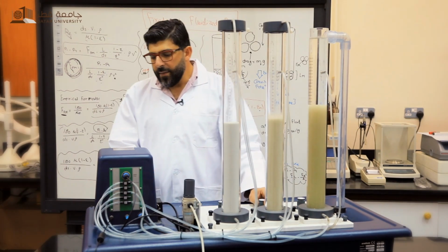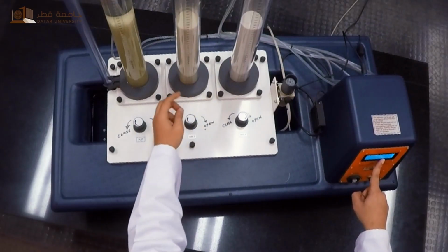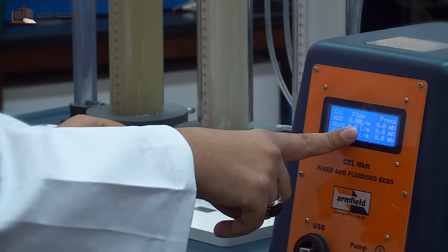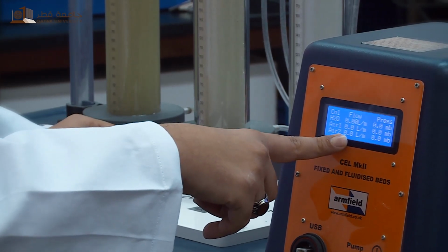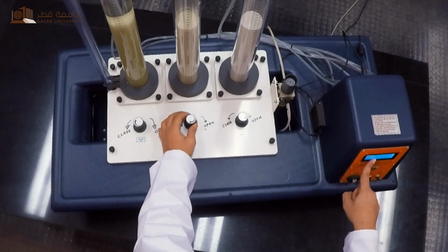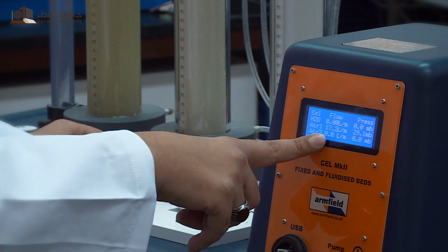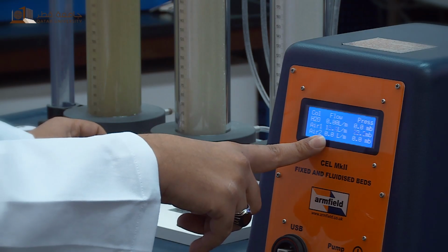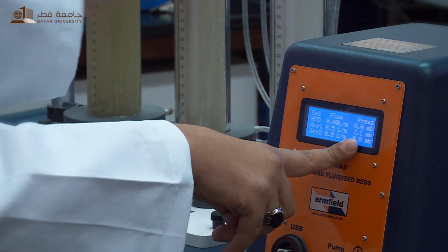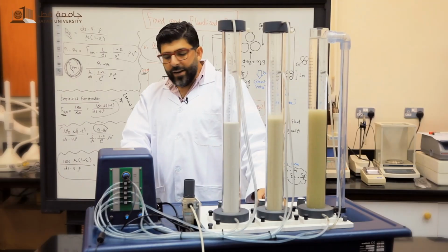Before starting the second part, the difference between them is only the size. So we'll start with this one. It's exactly the same as the water in terms of the process. Now, air 1. The flow rate increases, and there is an increase in pressure drop. Here you can't see any difference. The bed is still fixed because the gravity force of the bed is more than the drag force of the fluid. Again, I will increase the flow rate.